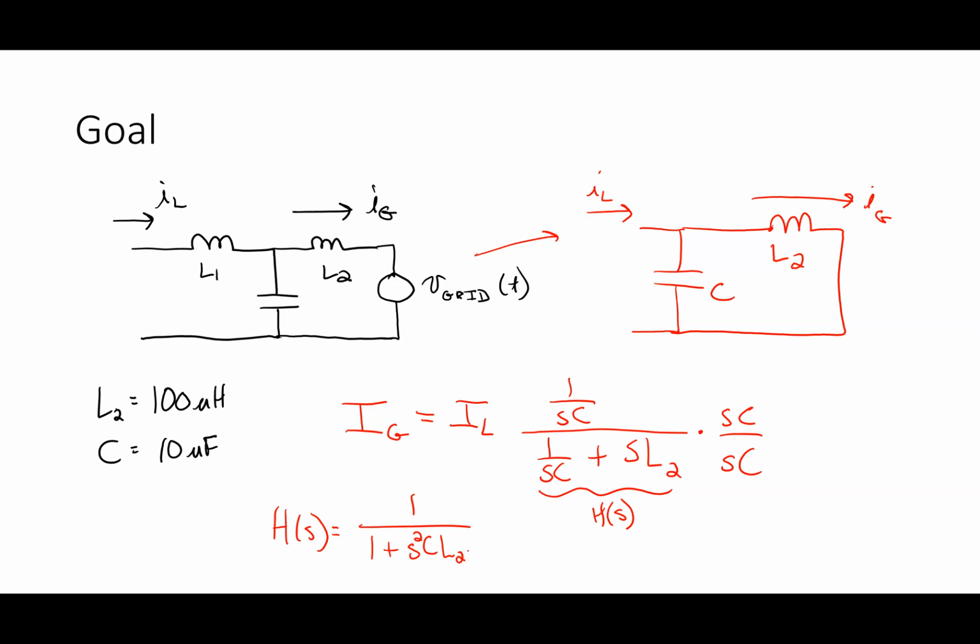Now, that guy has how many poles? Poles would make the numerator 0, right? Two poles. Yeah. Poles are the things that make it go infinite, right? So that means the denominator equal to 0. Think of the pole as really big. 0 is 0, right? So whatever makes the numerator 0 is a zero. Whatever makes the denominator 0 is a pole. So this guy's got 2 poles.